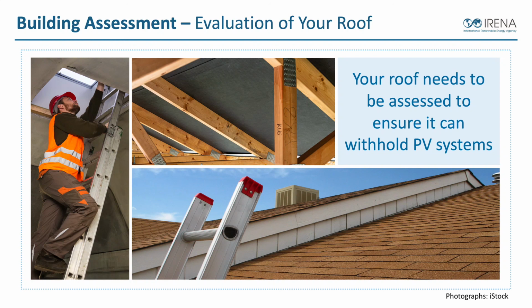So the quality of the roof, the age of the building, and the weight loading the building can handle needs to be assessed before we put a lot of solar in. Most of the buildings out there in the world that are well built and relatively modern can accommodate the weight of solar. Because like I said, overall, the weight of the solar is not that big of an addition, but it always does need to be assessed to make sure we're not putting extra weight on a building that may be already compromised.